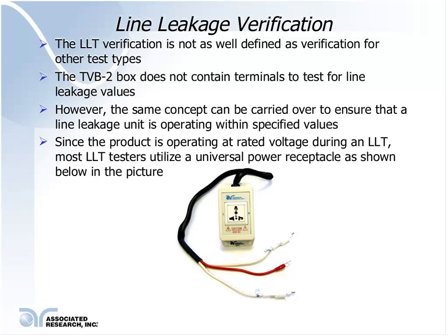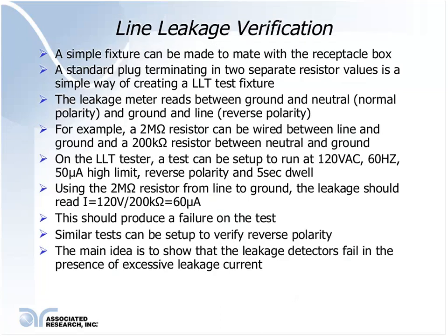The first line leakage test is set to 120 volts AC, 60 hertz, with a high limit of 50 microamps, and reverse polarity, 5-second dwell time.